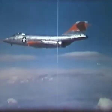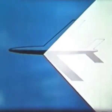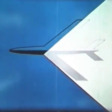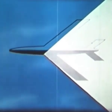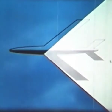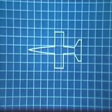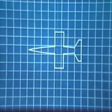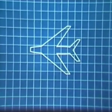The higher the speed at which an aircraft is designed to fly, the more highly swept it must be, so that the leading edge remains inside the marked lines. But there are limits beyond which the aircraft becomes difficult to handle, both at low and at supersonic speeds. So the choice is between straight wings, usually short and of low aspect ratio for sufficient strength, or highly swept, or delta wings.